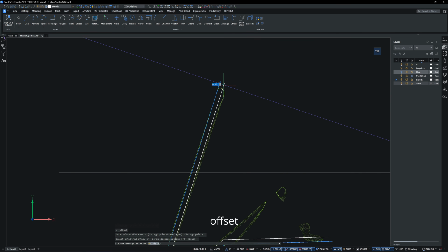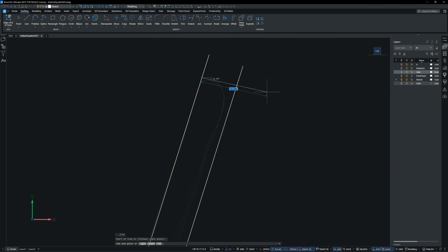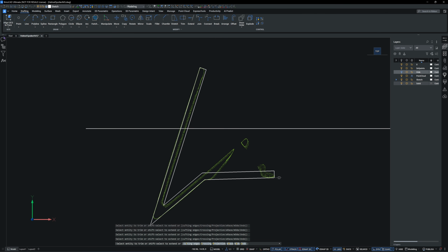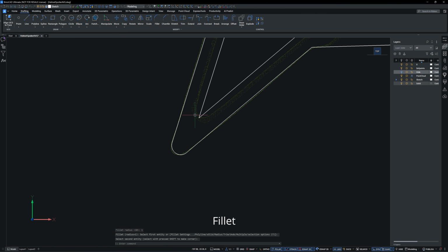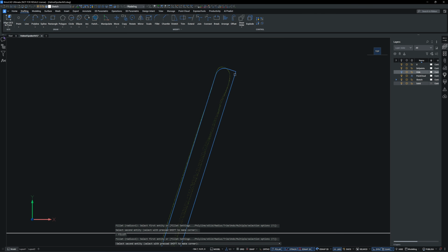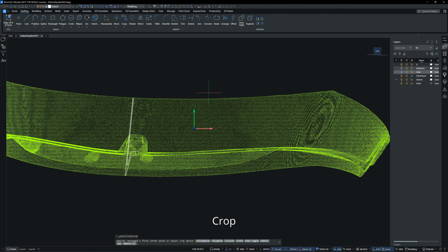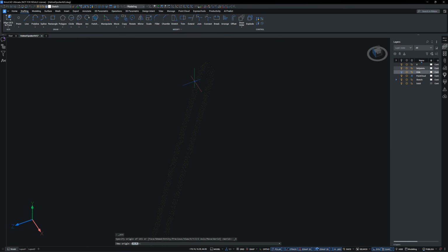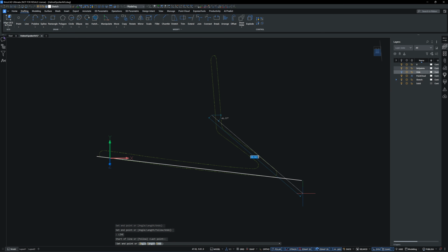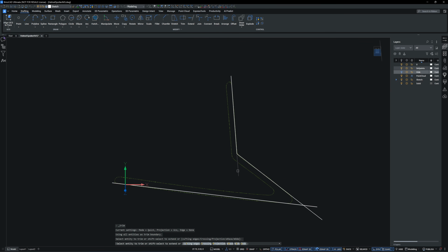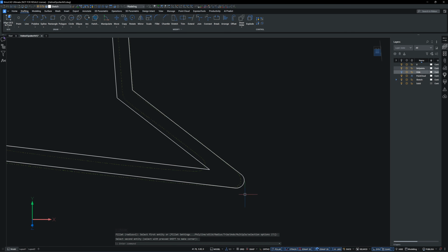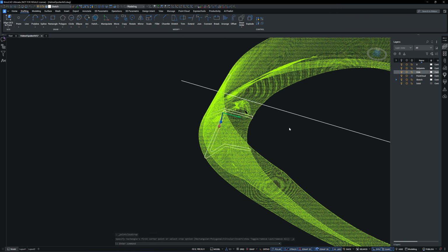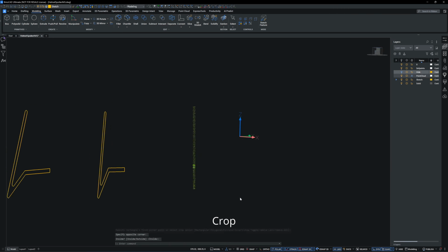For this section profile, I will omit the mounting hole and build it later. The profile I'm creating is thicker than the original, so I will set the wall thickness to 2 mm across the entire model. For the second sketch profile, I will create the sketch plane using the UCS 3-point method, snapping it to the cutting edge of the point cloud.